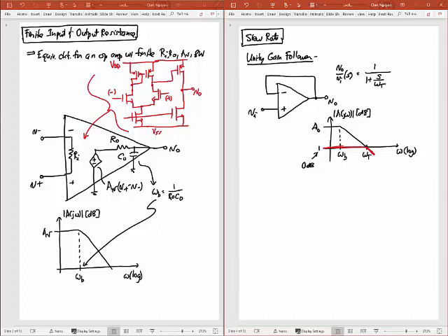This is a very important thing to be able to do. Right? I knew nothing but the new gain of my op-amp in feedback, and I was able to plot its Bode plot. So this Bode plot is for that transfer function. Okay? And this black thing is the open loop. The black thing is for the open loop transfer function, meaning it's for A of j omega.